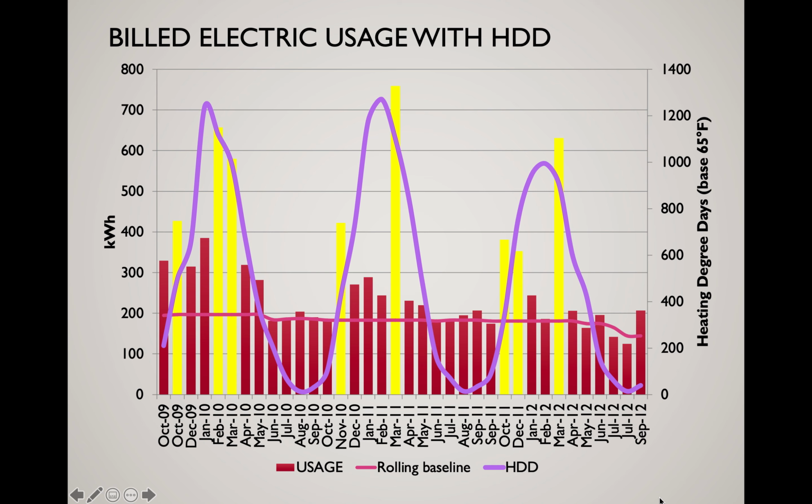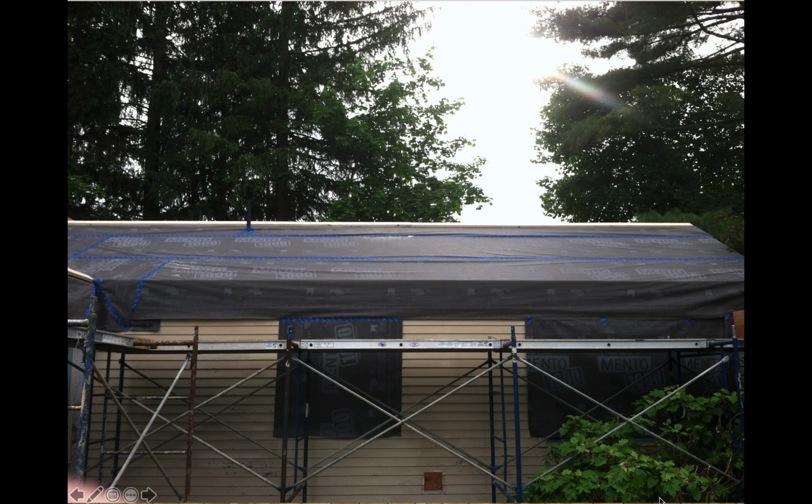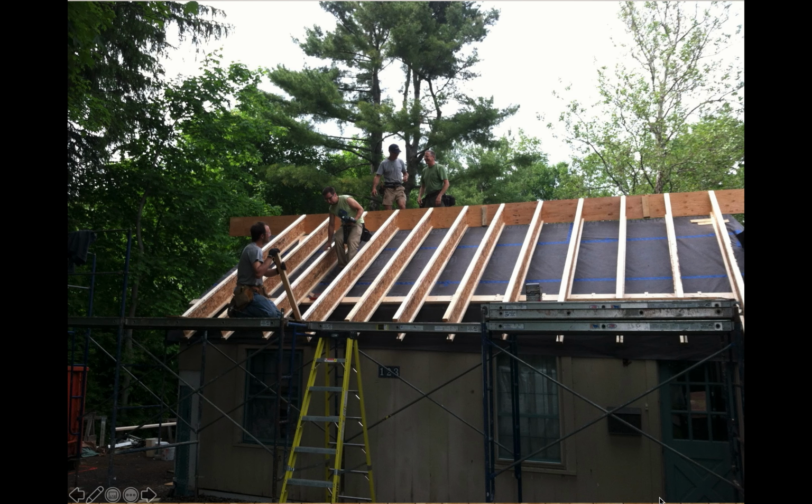So I used energy billing analysis to figure out that most of my energy spend at this point was actually happening in that newer section. And so I knew I had to do something about it. But this time, I was able to plan better, and I realized that I was going to need to cut the eaves completely off the house and make a continuous air barrier. And this is much closer to what is now the optimum approach for creating a continuous and contiguous air barrier for most framed buildings. And then on top of that continuous air barrier, I put exterior insulation.